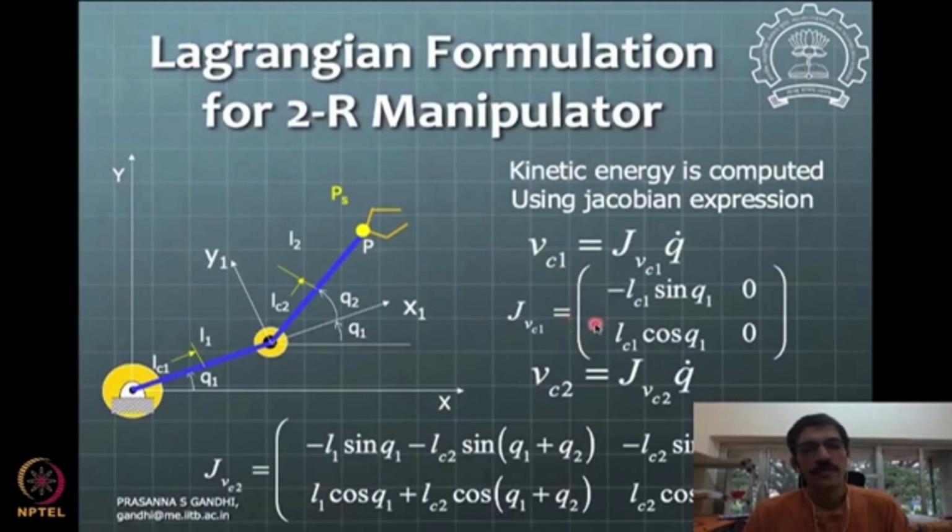That's how you get the velocities in terms of a Jacobian matrix, and this Jacobian has some value. We'll see what value it adds, especially for robotic systems. It has significance when the Jacobian becomes a singular matrix, then you'll have a problem in operating that robot. So maybe that much is enough for the discussion of Jacobian. But this is an interesting concept and way to write the equations of velocities of linkages, especially since there are CGs here for the sake of writing kinetic energies.